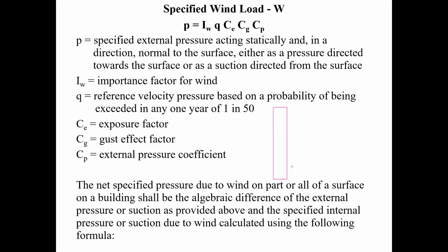That's where they talked about the algebraic difference, because, like I said, I shouldn't have erased that sketch. Here's my stud. The wind load is here, a positive value, and this is going away from the surface, a negative value. So when I take the algebraic difference, I take this minus this, and I literally have to add that to that, because they're both acting in the same direction. That's what the algebraic difference means.